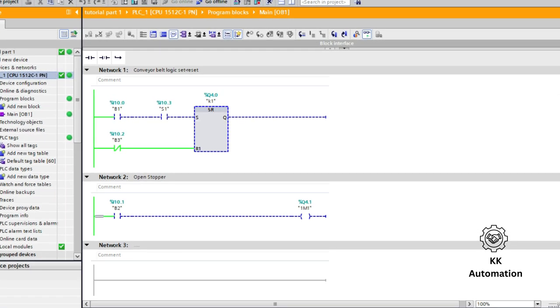Let's understand the signal flow. B1 isn't active, so the current path is broken. B3 is a normally closed contact. When inactive, it allows logic to flow. We need to invert B3's behavior in the simulation.